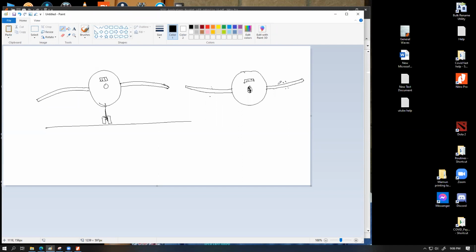So we can place some of the strain gauges over here. For example, if I now draw the top view of the aeroplane, here's the aeroplane, and this is the tail of the aeroplane. This is the tail wings, and let's say this is the large wings of the aeroplane. This is the top view. What we're going to do is put these strain gauges lengthwise in this fashion, figure not drawn to scale, where these wires are going to be in parallel like that.